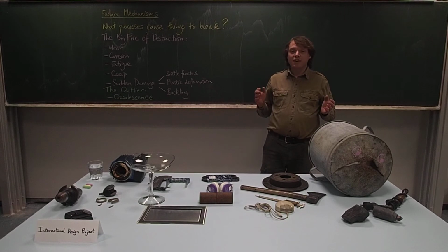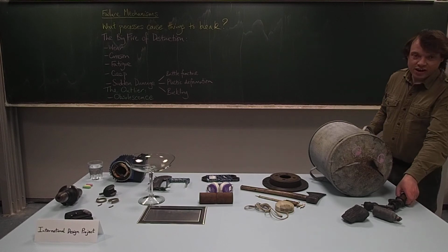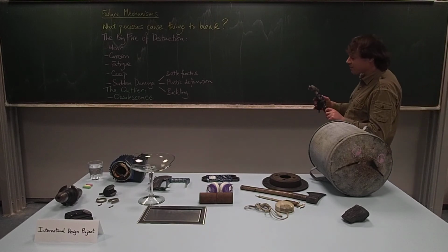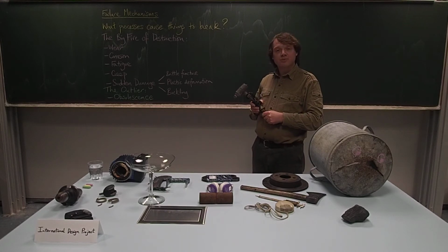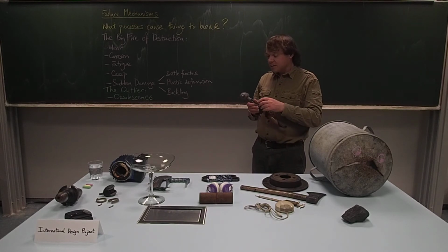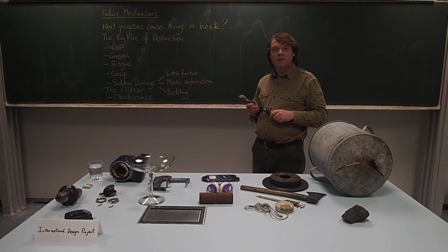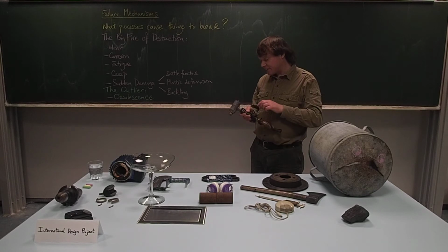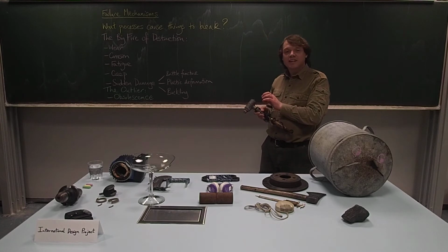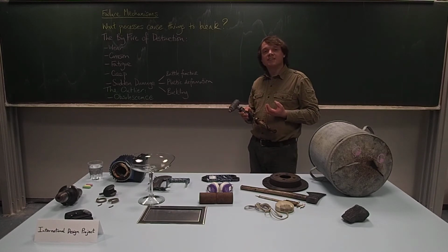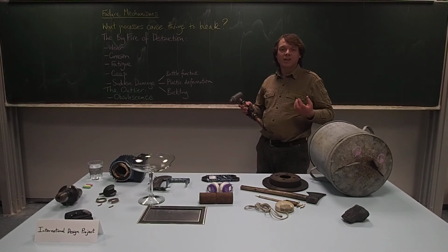iron oxides are usually very bad electrical conductors and thermal conductors. So here you can see a soldering iron, and this is a big hammer type soldering iron of about 300 watts. And you'll see on the end here, this is actually not very good for soldering anymore because the copper has become corroded. You may find that the connections where the wires are then screwed onto the heating element might also become corroded, and you might find they will then stop working. They'll stop allowing current to pass.